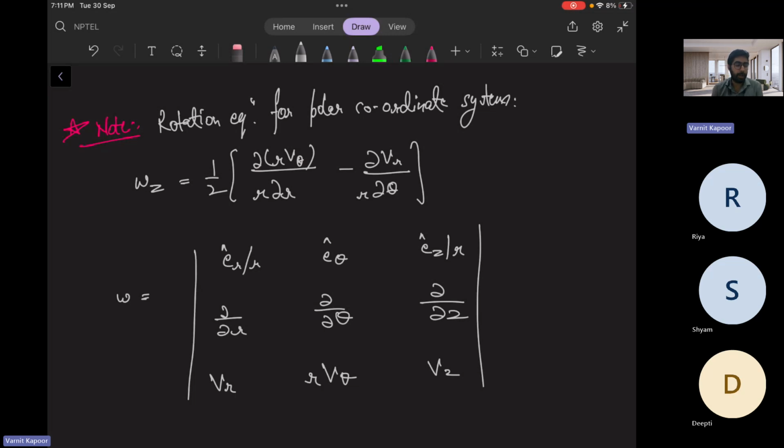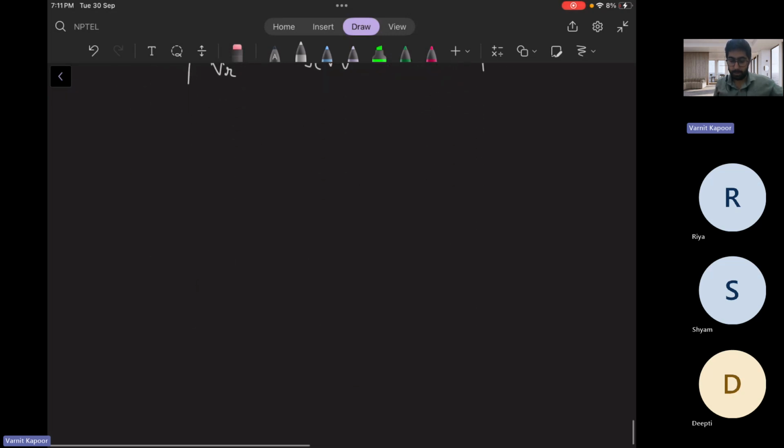So if my external torque is present, that means forced vortex. That means I'm giving it, it will be rotational. Forced vortex is rotational, whereas free vortex is irrotational. We don't give any extra external torque to it. So let us write vortex motion.